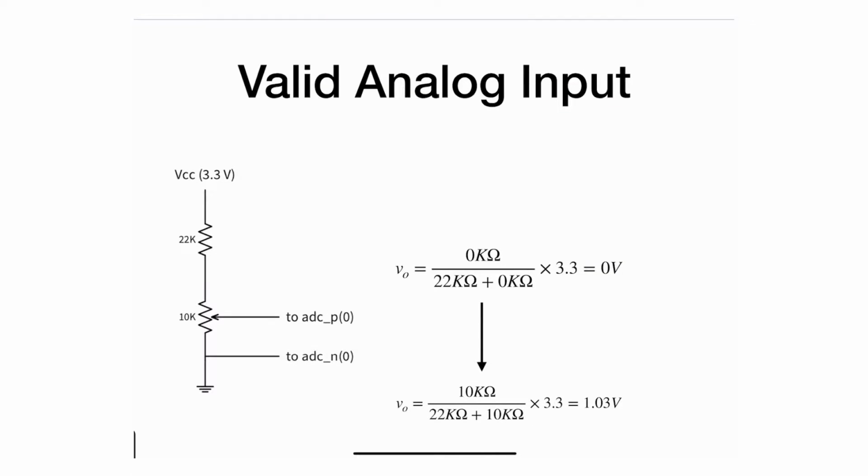We now move into the test program for the XADC, but before I just jump into that, I want to talk a little bit about basic circuits. Specifically, the ADC we're using expects differential input, so it has a positive and negative port for each one of the channels, and it's operating in unipolar, so the negative port should be connected to 0, to ground, and the maximum that it can actually see is 1 volt.